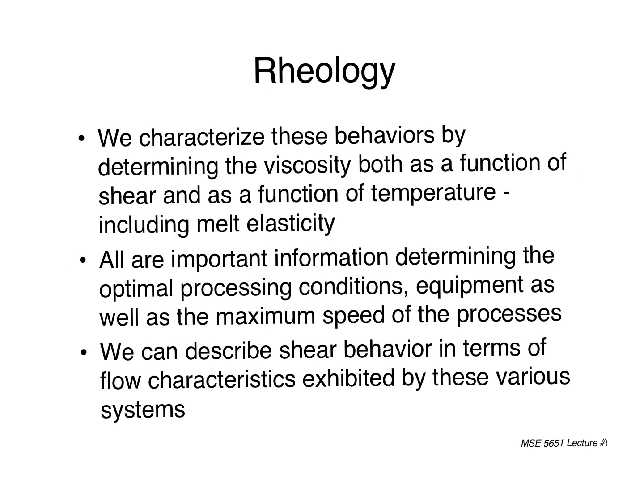And then we also characterize these things by determining the viscosity, both as a function of shear, meaning that we shear the heck out of it with these mixing systems, and I'll give you a video of that, I think in the next lecture, and as a function of temperature, including the melt elasticity. So we want to know how much shear is necessary to establish a certain viscosity, and we also want to know what happens to that as we heat it up, which is also part of the injection molding process. So we start at room temperature, not high enough temperature to make polymer melts. We have to go to high temperatures like 200 degrees, and we form the object, and then we take it out and we put it into a furnace and burn away the polymer. But this is all part of how we establish how well a material is going to behave.